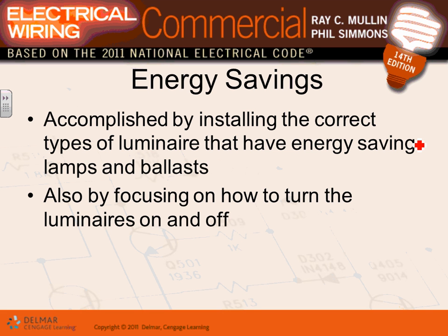So energy saving, we talked about this one, guys. Start with the type of luminaire that you pick, including energy saving lamps and energy saving ballast. So when we did the COMcheck, Karen, you guys did COMcheck with me. When you were doing COMcheck, we were picking the type of lamp that we're using, which will be installed in a luminaire, right? And the ballast, electronic ballast. You guys remember that? And we have control means at the end. What type of control means?